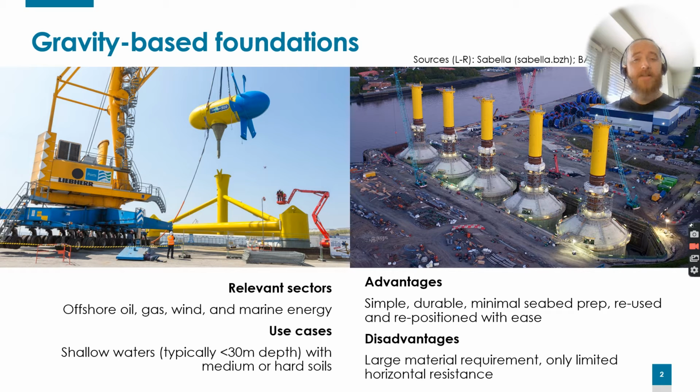The advantages of a gravity-based foundation are that it's simple and that, with the right equipment, it can be repositioned and reused with ease. The disadvantages are that some designs can use a lot of material and provide only limited resistance to horizontal loading.